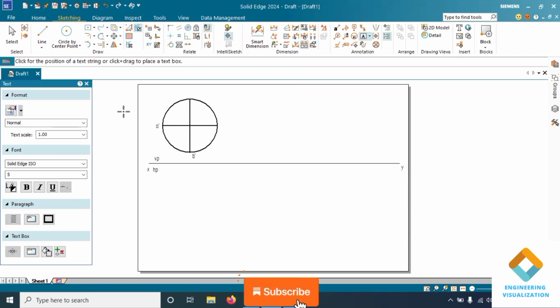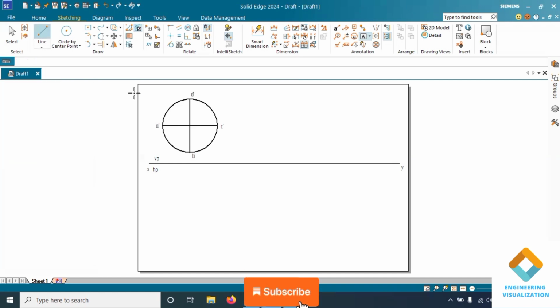Watch the video till the end so you can understand the concept and how to construct it in the Solid Edge software. I think I have not done this problem on my YouTube channel. Using the extend to next command you can extend these lines.